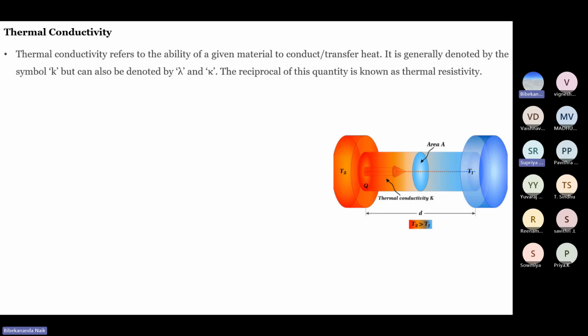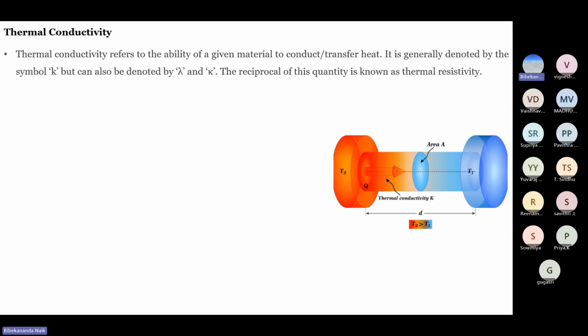Like we know, different materials have different coefficients of thermal conductivity. Thermal conductivity basically represents the ability of that medium to transfer heat. Suppose we are considering air, and we know air is a very good thermal insulator. That's why houses are generally made with two roofs, and in between, the air is trapped, so that heat will not transfer from the top roof to the second layer.